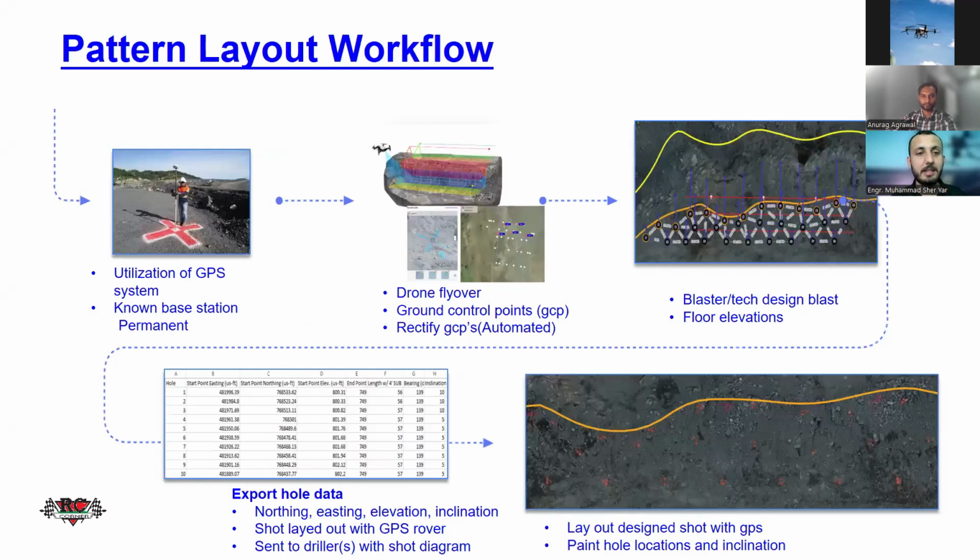For a detailed workflow, you need to have ground control points using the DJI D-RTK 3 mobile base station. You can easily capture the ground data as per the control points. You can place a permanent benchmark there, and also just fly over the area and take the imagery.